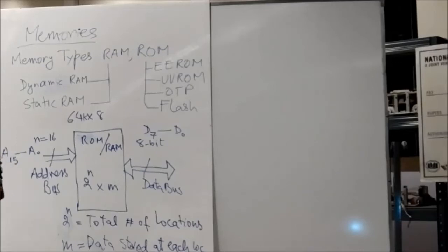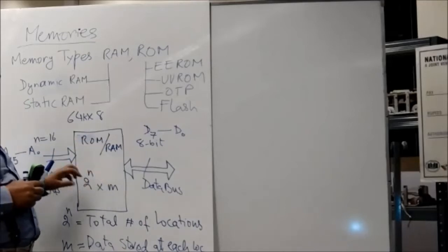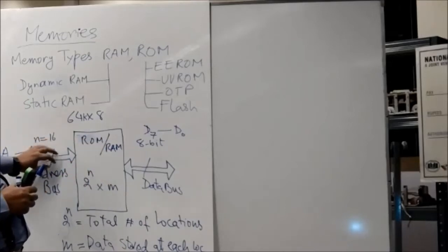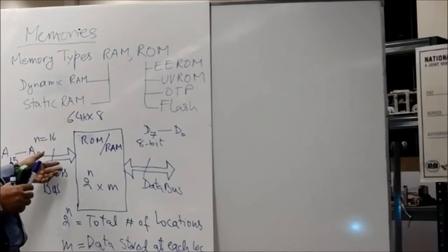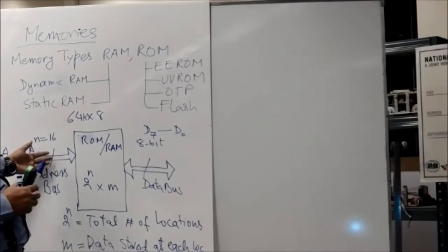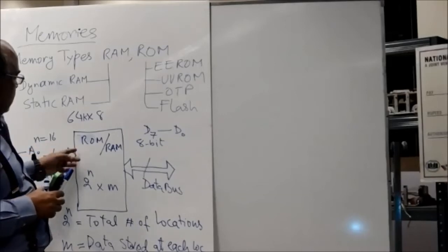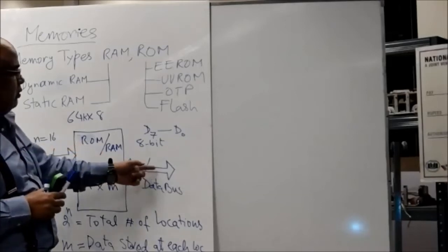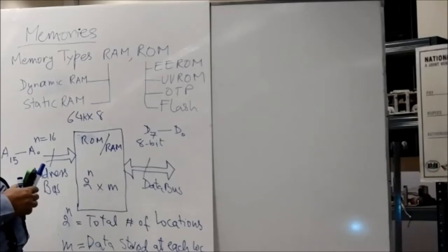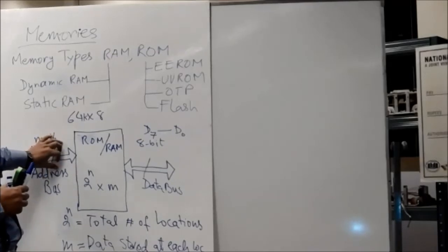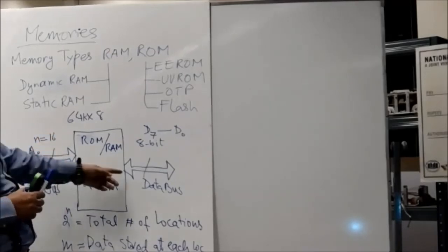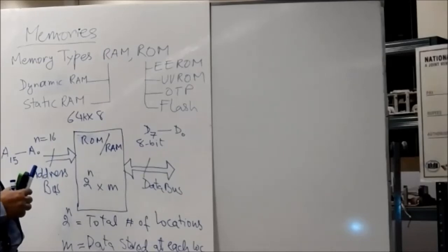In the case of ROM, it is even simpler. Once you have written your data onto ROM, you give any address using logic switches. When you give an address, you will have 8-bit data at that memory location appear at the output. Since there are 16 switches, you can generate 2 raised to the power 16 different addresses, and each location gives you 8-bit data at the output.